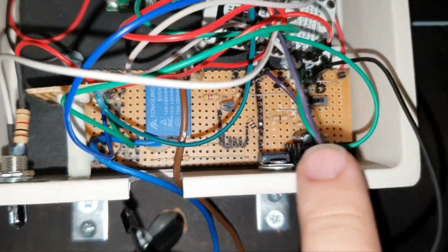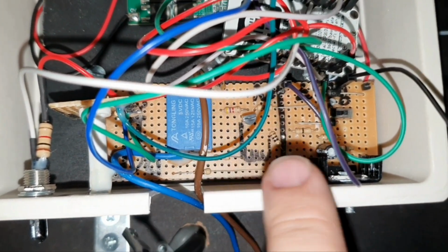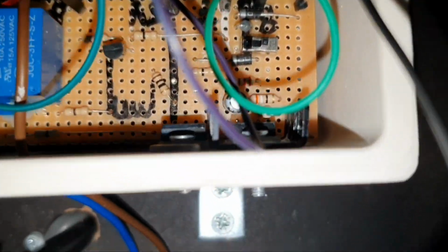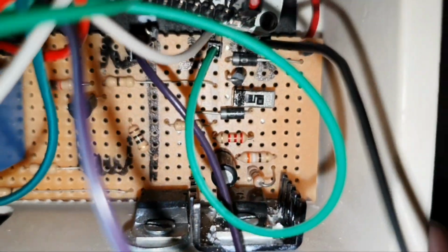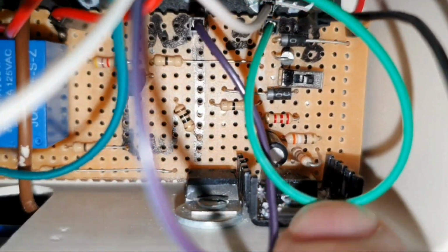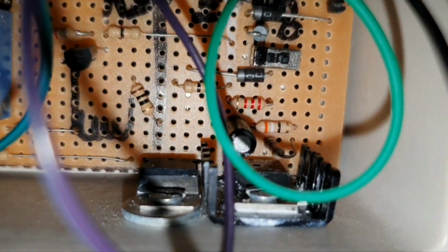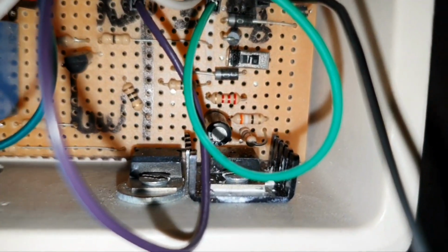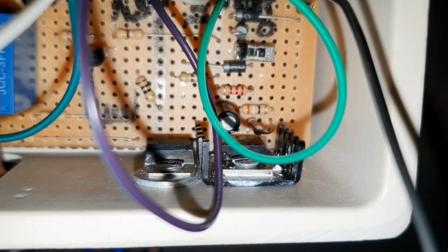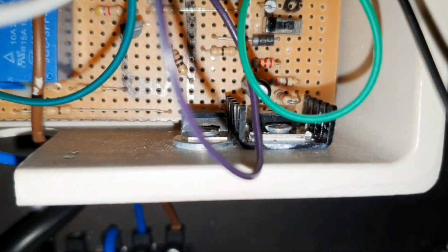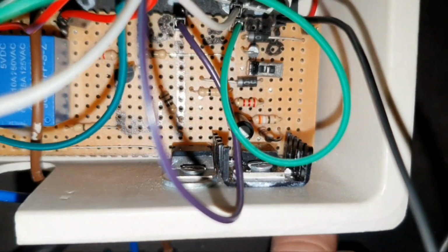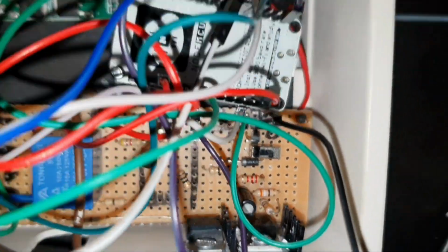Now this circuit board that has been soldered onto Vero board, on this side is the power supply. So I will just go closer. We have the LM317, on the right side there, that is the adjustable voltage regulator, and that is used to step down 24 volts from the solar panel to approximately 9 volts. I think it's closer to 8 volts of charging voltage for the batteries.